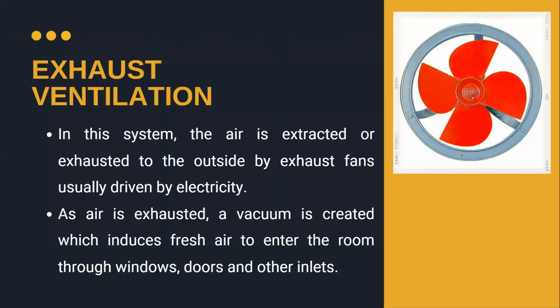Exhaust ventilation. In this system, the air is extracted or exhausted to the outside by exhaust fans, usually driven by electricity. As air is exhausted, a vacuum is created which induces fresh air to enter the room through windows, doors, and other inlets.